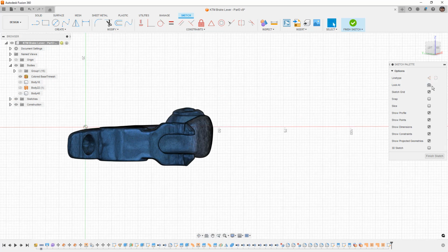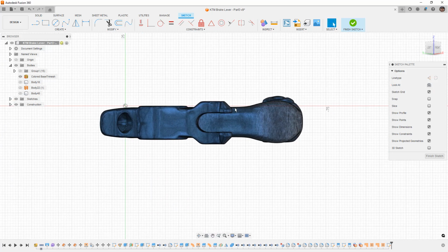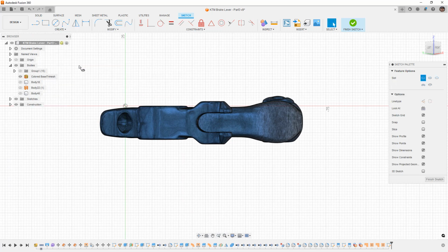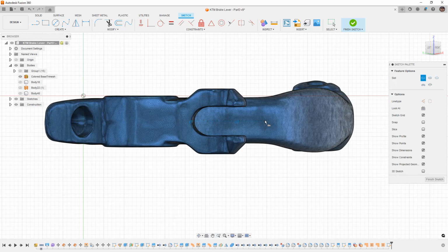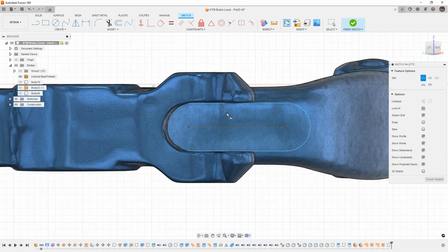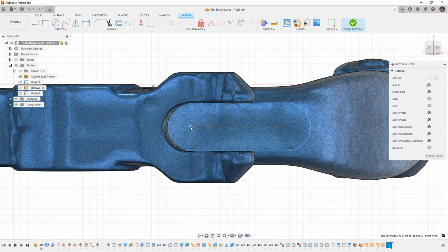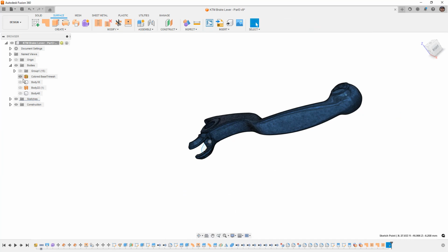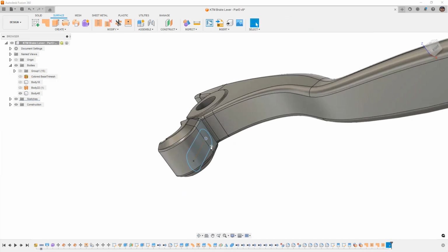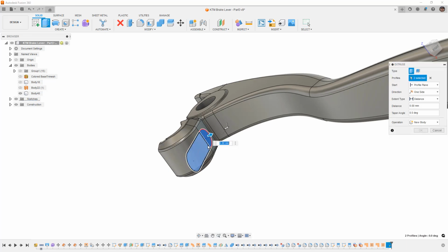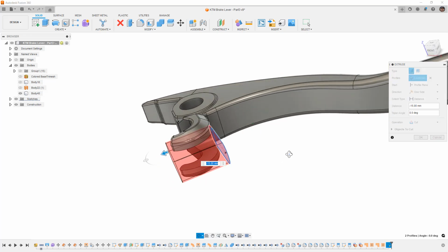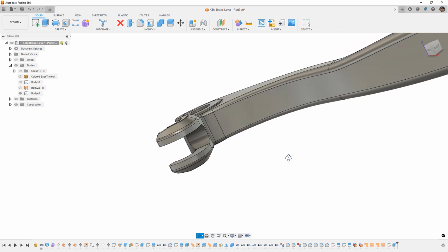And basically what I want to do is just create a slot. Just go and select the slot tool and get it close enough. Again, I'm not super hyper focused on the dimensions for this model. If you're going to manufacture something, you certainly do need to make sure that all the dimensions are right. Not really worth it for what we're doing here, but the intent is still there. Make sure that we do go back to the solid tools, E to extrude, and go ahead and pull it through the entire model. We'll say OK.